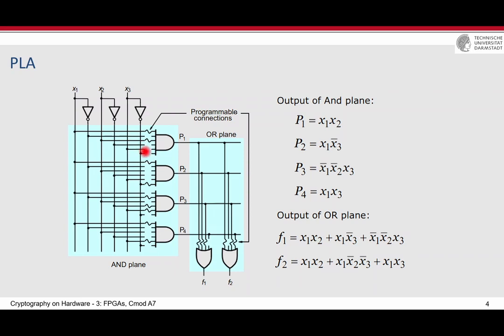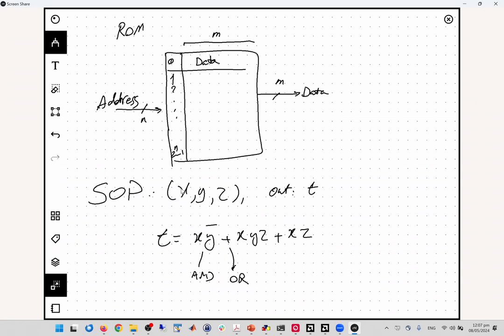And of course, this was designed like this. If they are not connected to anywhere, then they should be connected to the VDD. Otherwise, if the input of the AND gate is connected to 0, the output is always 0. If it's an AND gate, there are 3 inputs with the fuse. And this is connected by a resistor to the VDD.